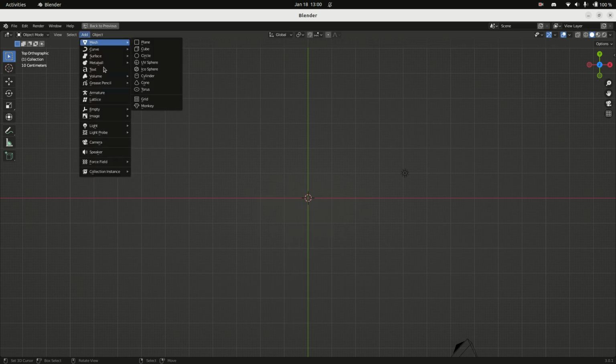And you can see that Blender supports a wide variety of things we can add: curves, surfaces, metaballs, text, grease pencil drawing, armatures. I do most of my work with mesh modeling, since most of the work that I'm doing, and the whole point behind this class, is to create things that we're going to be using in other applications. So I am going to add a monkey.